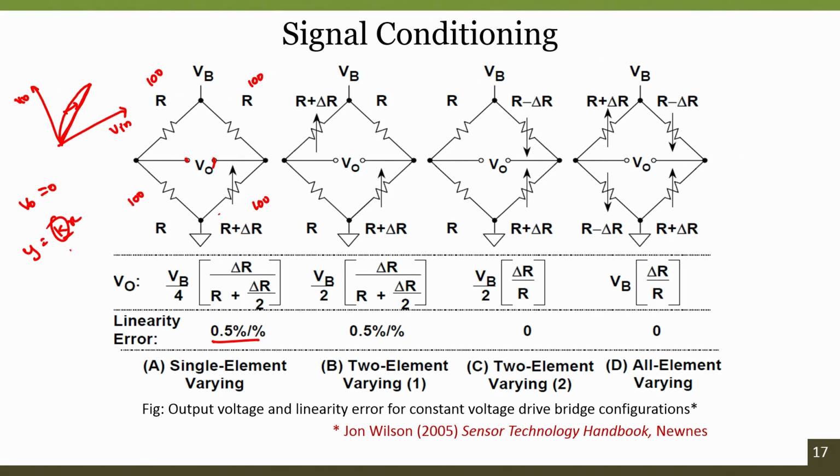What do I mean? Imagine k is 0.5: for an input of 1, y should be 0.5, and for an input of 2, y should be 1. But if for an input of 1 the scaling factor is 0.5, and for an input of 2 the scaling factor is not 0.5 and is varying with respect to the input, then it is not satisfying the principle of scaling, which means that it is nonlinear. That can be simply understood because k should be constant, so y should always be proportional to x. If this particular property does not satisfy, we can simply say the system is nonlinear.